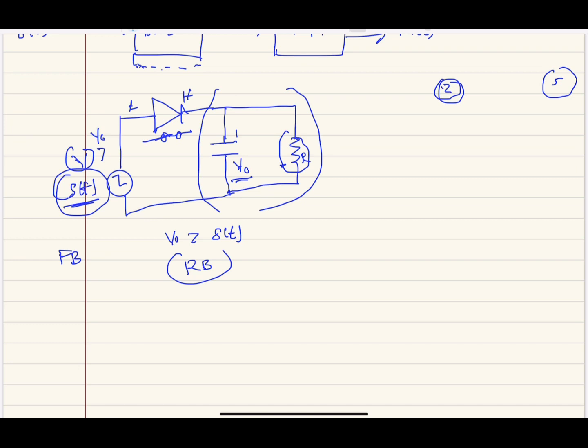That is, it must have a low time constant in terms of charging. It must reach its maximum level within the shortest possible time, but it must have a very long discharging time, which is the time it is discharged through the load, the resistor. That means it must have a very large discharging time constant.